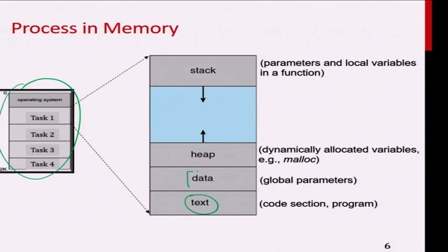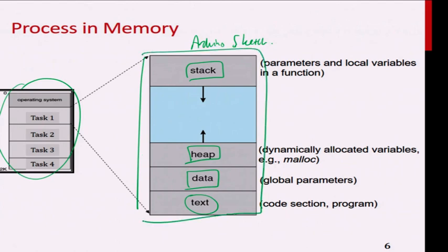And when you write some code, there will definitely be data. You will always be using the stack because you're going to have function calls. You need to push variables on the stack and retrieve variables. You also have dynamic memory allocation, for example malloc, where you use the heap. So you can imagine that in the past, when I did my Arduino sketch programming, when I compiled my code, I only got this one thing, correct? Because I wrote it as a single while loop, with all the tasks, function calls, my arrays, my malloc, everything inside one big while loop. So when I compile my code, the entire code comes inside this text section here. And all the variables I declare go into the data section. So effectively, my whole microcontroller snapshot of memory usage is this.